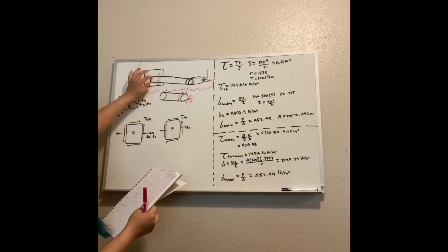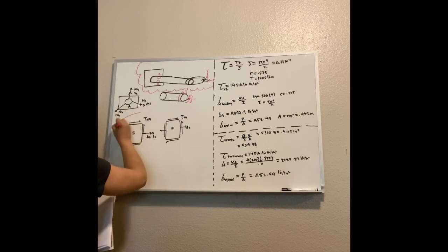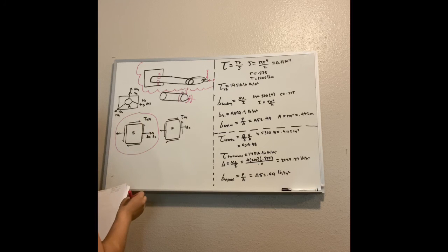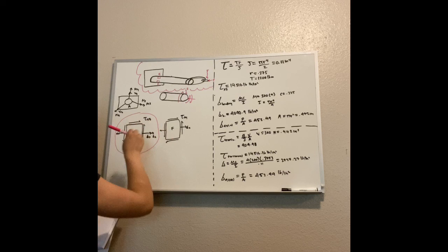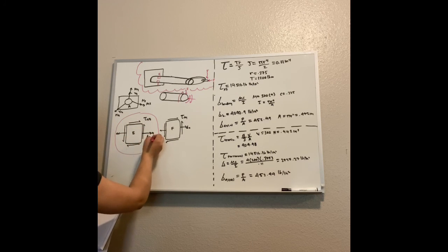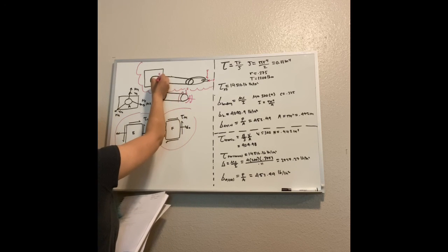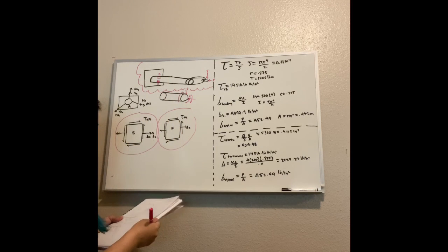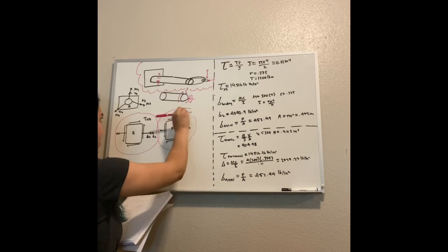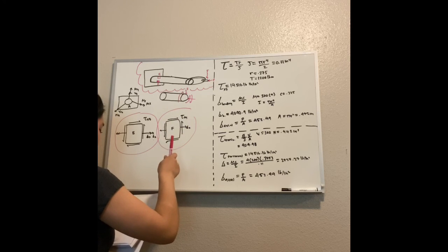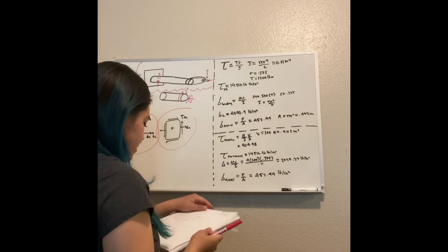If we zoom into these stress elements, this is stress element E that I've drawn. For stress element E, we have a torsional force in the xz direction, and we also have an axial and a bending force. Now for F, which is this one right here, we have a torsional and a transverse shear, which is going this direction, and then we also have an axial and bending force. So now we're going to start looking at the stress components of E.